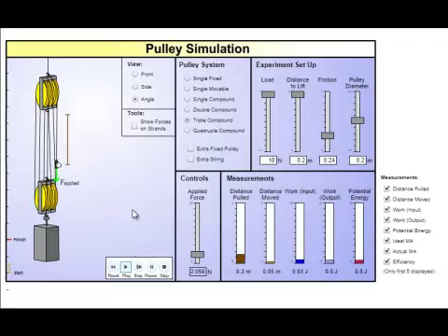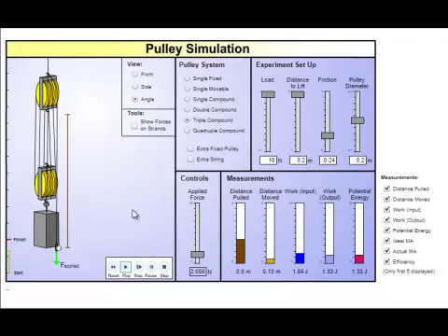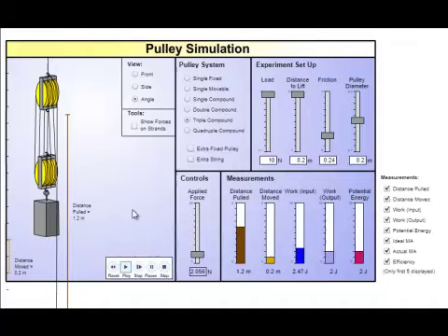In the meantime, obviously it makes sense that the line segments, there are 6 of them, also gives us the ideal mechanical advantage of 6. That much I can give away. And that as I'm lifting this here 0.2 meters, I should come up with 1.2 meters for the hauling line. In fact, it's going to show us that in just a moment, right? Oh, it is getting a little off screen here. Oh, it really goes off screen. Okay. There it is, 1.2 meters, right?